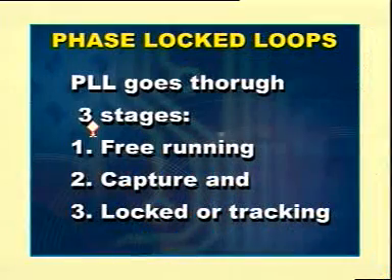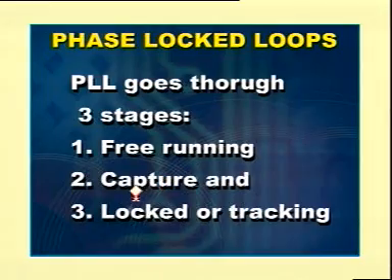After getting the phase locking, the circuit will be having a stable frequency, that is Fs equal to F0. There may be slight difference between Fs and F0 with respect to phase only. So, this phase variation may be adjusted within the circuit. Okay. So, here this circuit is having three types of actions. One is free running, next one capturing, next one locked. After locking, the circuit keeps the VCO frequency always stable.